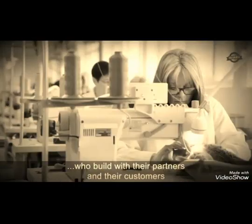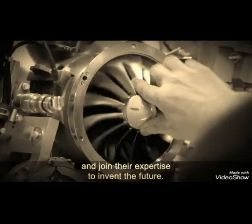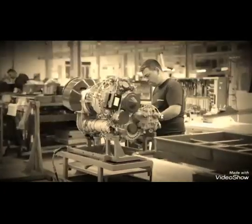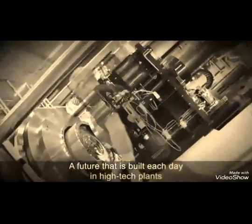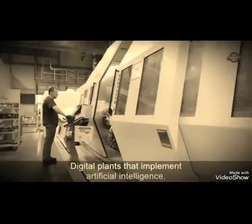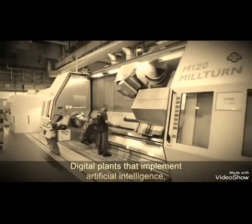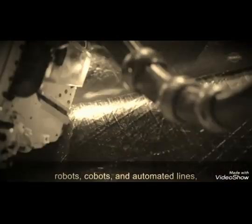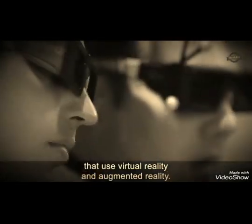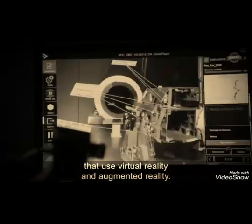After weaving, the preforms undergo an impregnation process where they are infused with high-performance resins. This impregnation fills the gaps between the carbon fibers and forms a solid composite material. The composite is then cured under controlled temperature and pressure conditions to achieve optimal bonding between the fibers and the resin matrix. The resulting 3D woven carbon fiber composites exhibit high strength, stiffness, and excellent fatigue resistance.